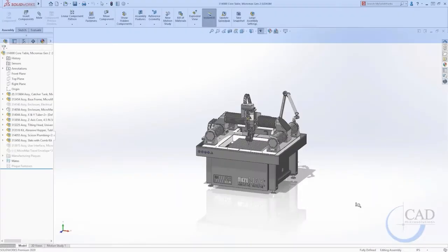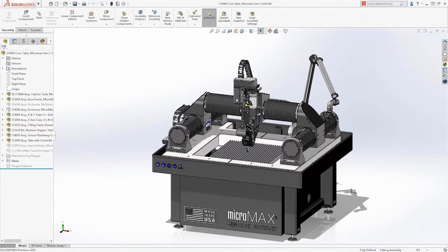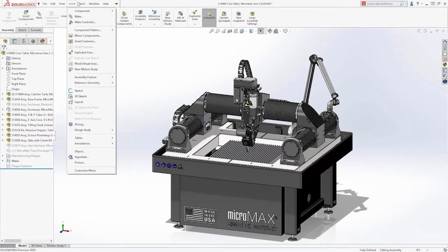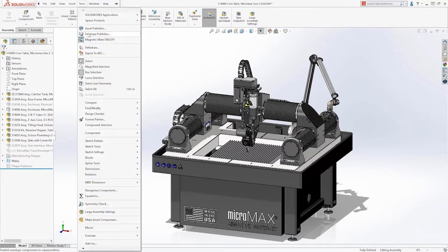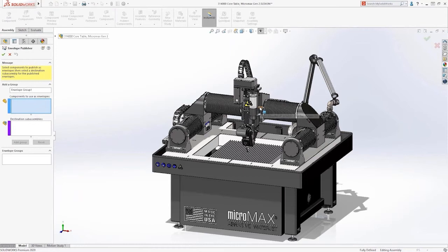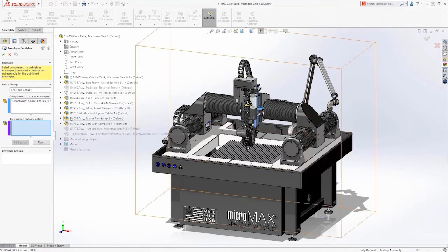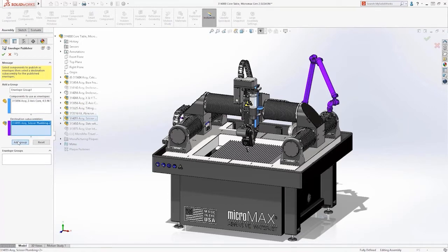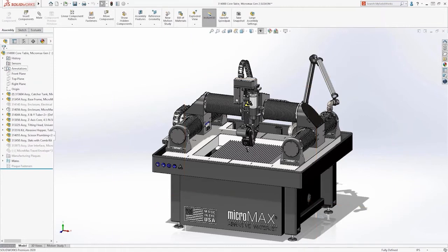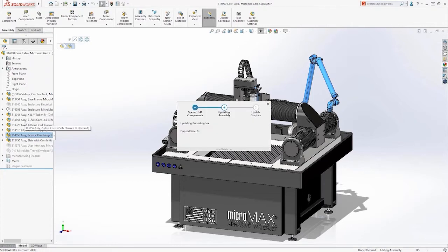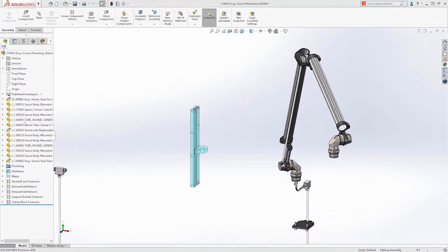Taking a look at the envelopes, top-down design is fantastic, but sometimes working in the top level assembly is a little bit slow. It's the part of your assembly that has everything in it. So that's when we want to have the ability to reference things in the sub-assemblies. That's where we use the envelope publisher. We take entities that we want to reference in one subassembly, and then we select a different subassembly that we want to copy them over to. We're creating the envelope in that subassembly. This means we don't have to have data reuse where we have something happening in multiple subassemblies. We don't have to have things not making sense in which subassemblies we're putting them in. And it means we don't, again, have to work in that top level assembly.